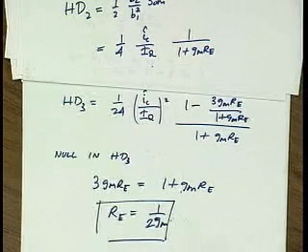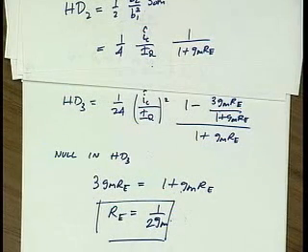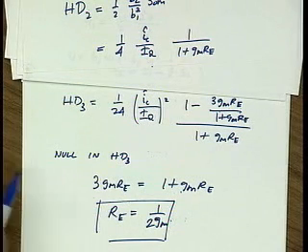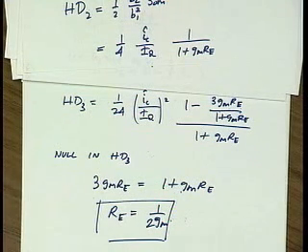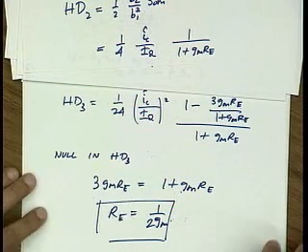Now you can see the problem because GM varies as a function of temperature. So if I get perfect distortion cancellation at one temperature, I change the temperature a little bit and RE has to change. Of course, it's not going to, so I don't get a distortion null.